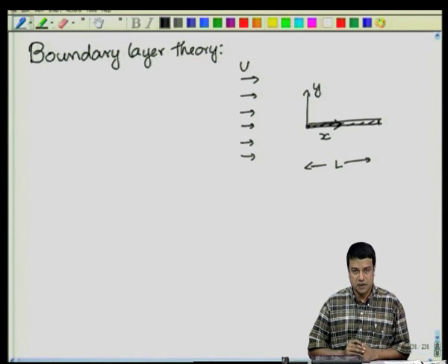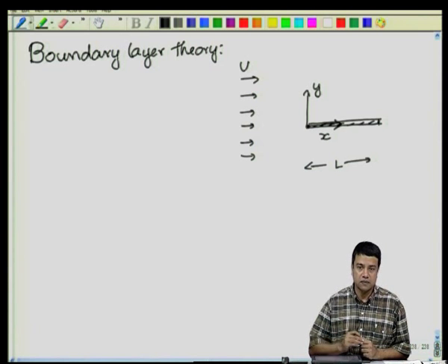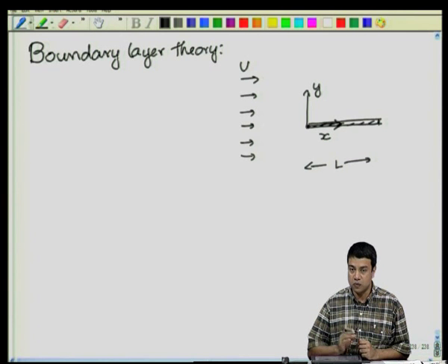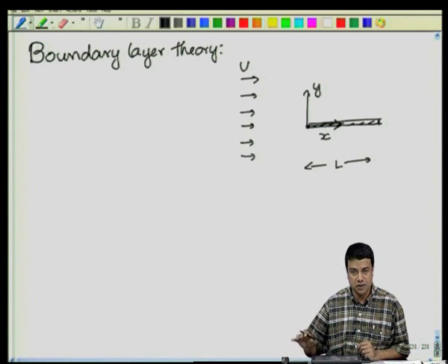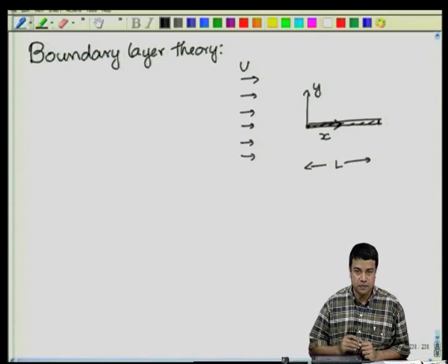So, far away from the surface, the diffusion from the plate will not affect the velocity field, because there are two mechanisms now. One is momentum diffusion from the plate, which takes place in all directions of course, but primarily the momentum diffusion that slows down the fluid at the plate is occurring perpendicular to the surface of the plate. Of course, there is also convection. The momentum is being swept downstream by the fluid and it is diffusing from the plate.